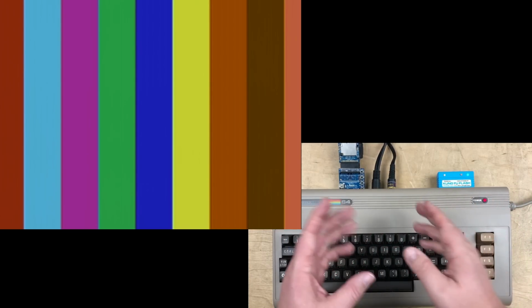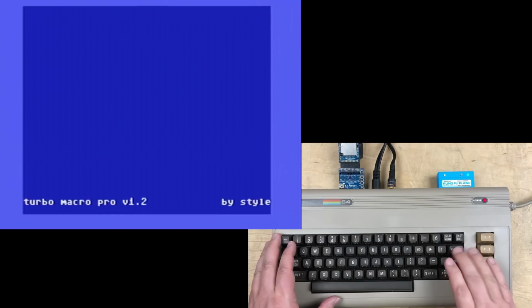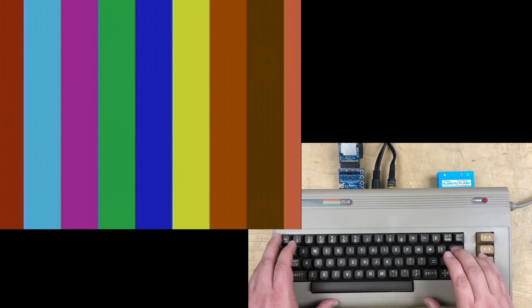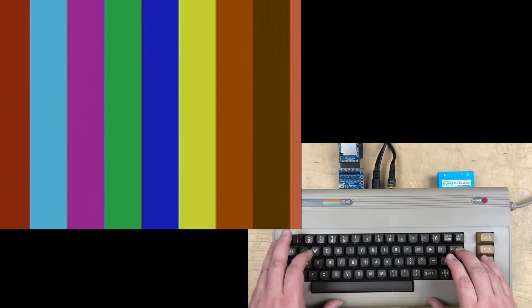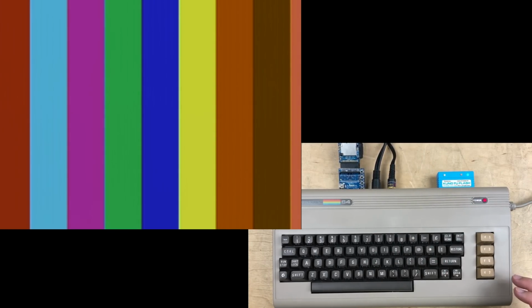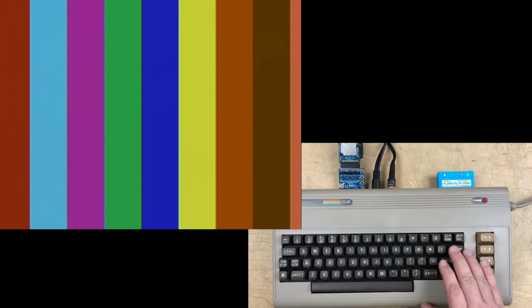Remember a while ago, red would show up at all different X positions, but now it's consistently at the left. And that's what that sync code is doing. But I think there's a case where that pink isn't always there. See, it's narrower this time. Sometimes it's 3 and sometimes it's 2. So there's still a problem. We're off by 1 cycle now. Okay, so we're going to have to solve that another time. But we've got almost a stable raster here.